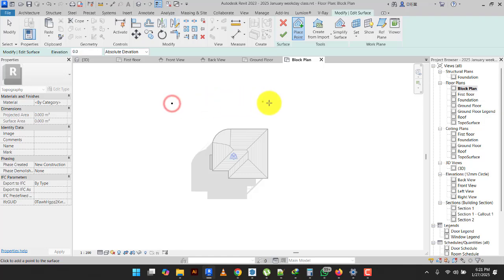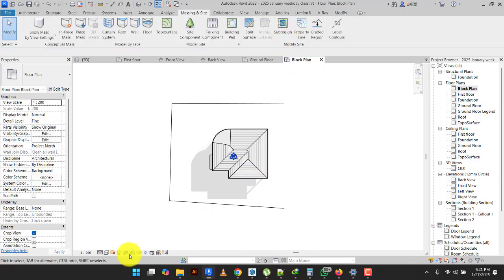So you click one point, click another point, click this point, and click this point. So you have 4 points. Okay. Then I'll accept. So when I accept, let me put up my crop region. You have 4 points. I was not seeing the other one because the crop was on. Remember crop. So these are 4 points you have.